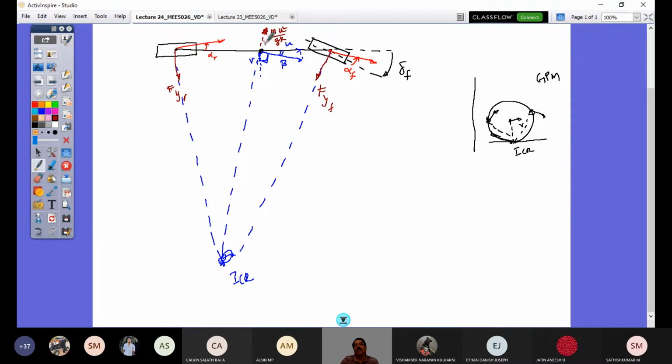So this is centripetal force alone if I don't represent any other force, or for a dynamic equilibrium along with an external force developed at the contact patch. If I bring in this, it is called a centrifugal force. It is just directed in this direction, as your centripetal acceleration is in this direction, right? Centripetal acceleration is in this direction towards the center of turn.